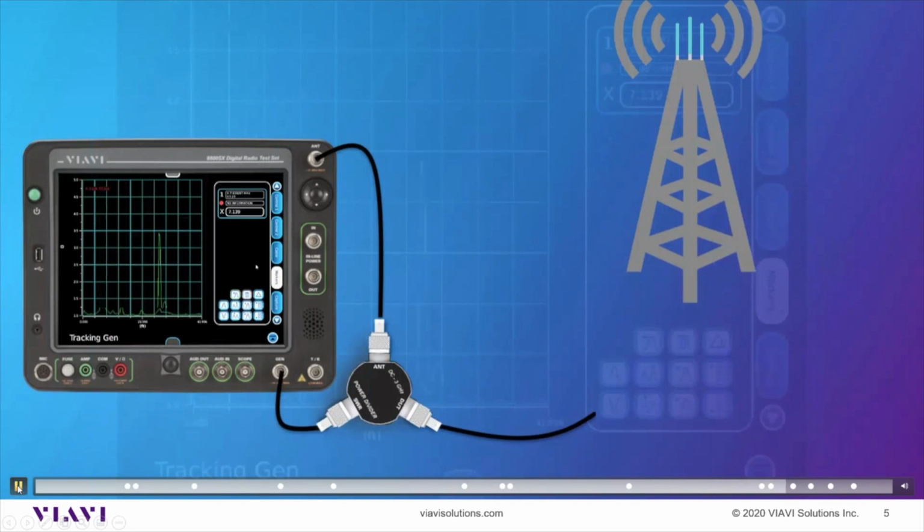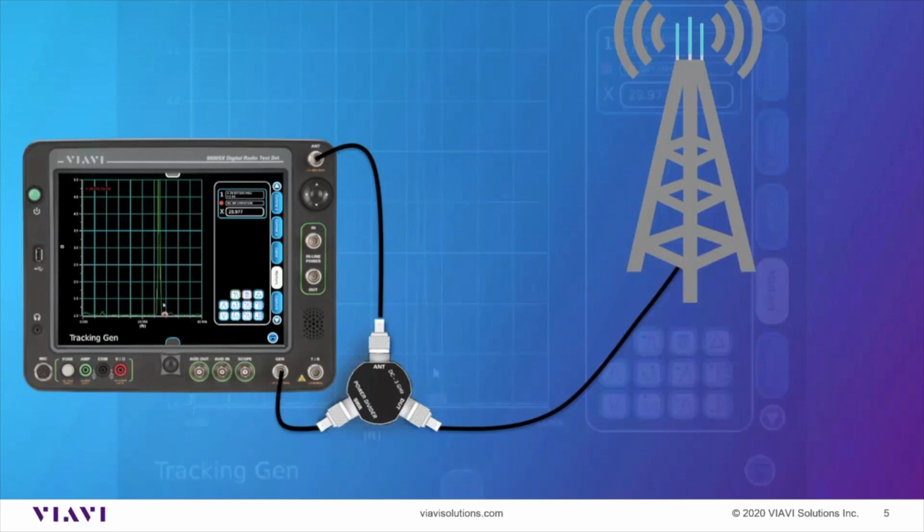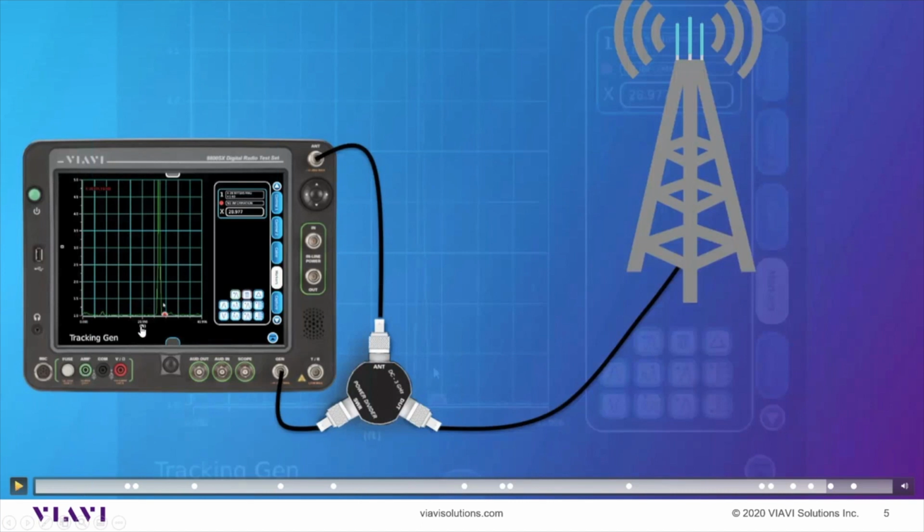And we're going to let it run a little bit longer here. Now, what I'm doing here is I'm moving the marker over to the right side of the signal onto that next peak there, the very small peak. But that's actually the antenna. And I'm going to prove that here by pulling the antenna off. So I'm going to scramble up the tower here, and I'm going to take that antenna off there. And now we see that the antenna has disappeared, and the end of that cable has gone through the roof.